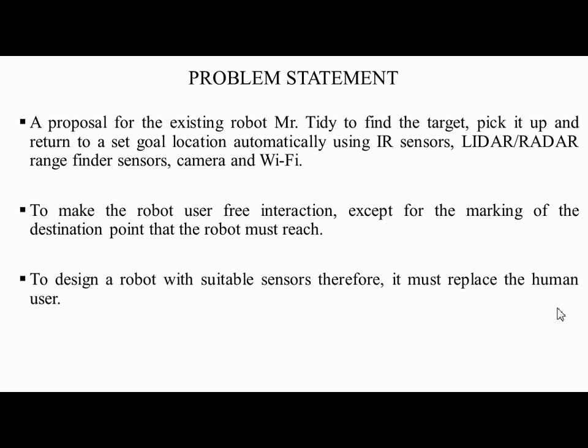Mainly I use the Arduino and AVR compatible microcontroller system, and the Arduino board is surrounded with IR sensors, which help not only with collision avoidance of obstacles, but also assist the robot to find an object easily and align the gripper accurately with an object.